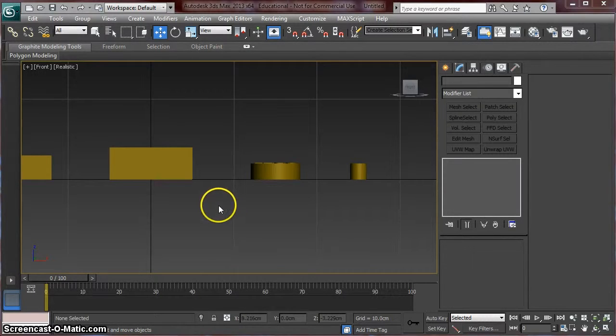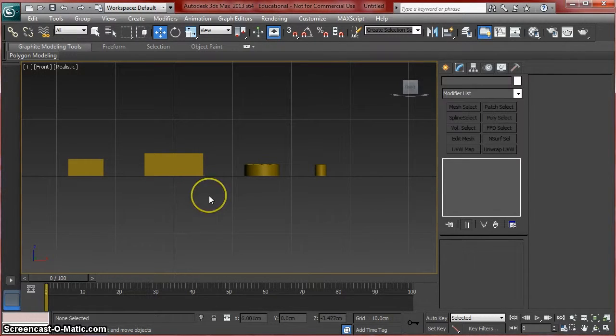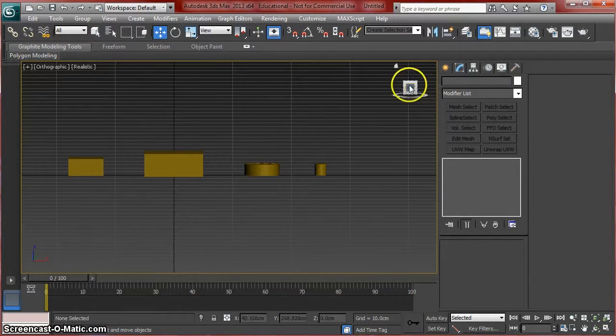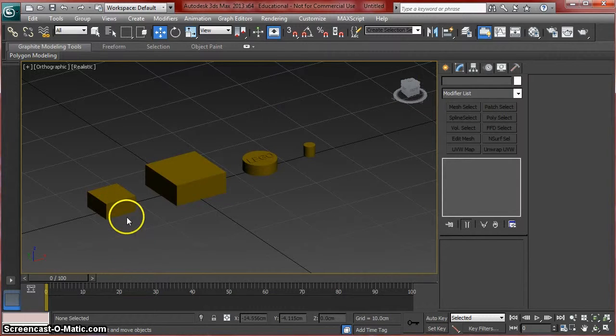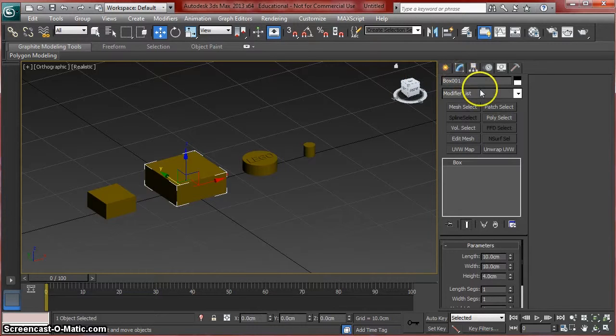You have now created the 4 base pieces that we will use to create most of our Lego blocks. It is good practice to name each object you create in 3ds Max. Select the main block and in the Modify tab, change its name to the following: M_10X10X4_main_block. Eventually, you will create your own naming systems, but I think you'll quickly get the idea behind my naming conventions.